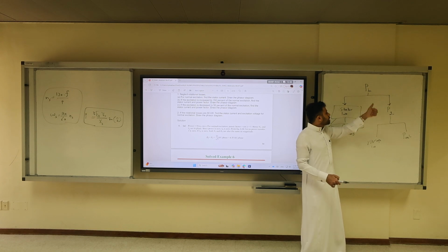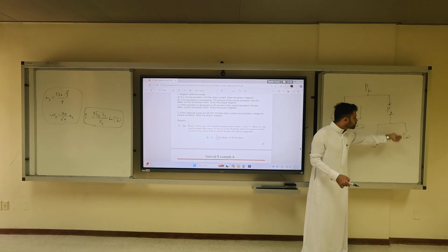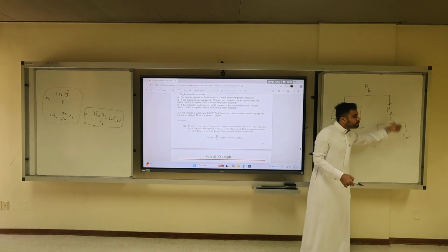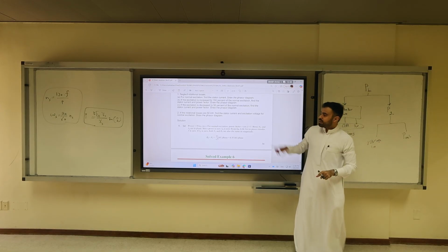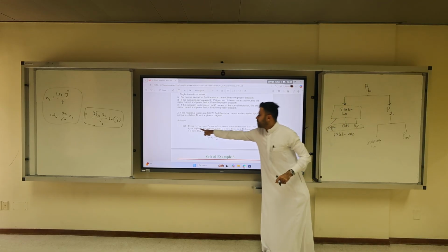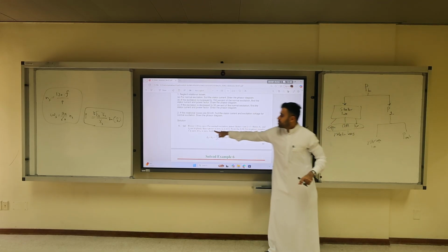Think about it. In part 1, if we ignore these losses, there is no air gap power because there is no mechanical load. Your input power is 0.